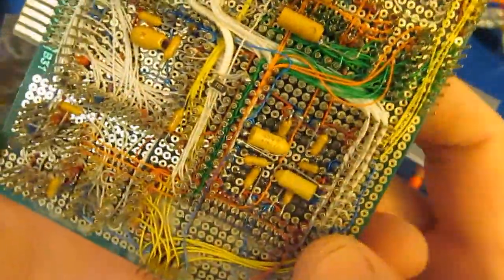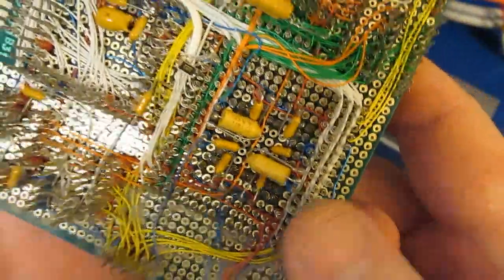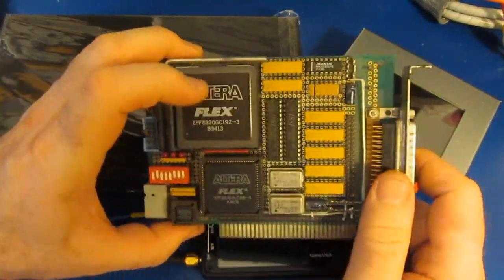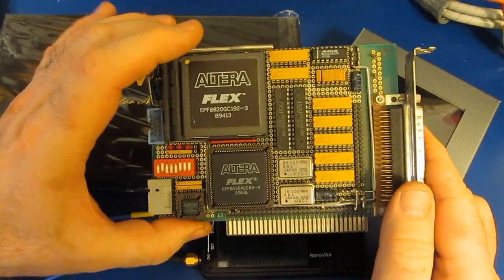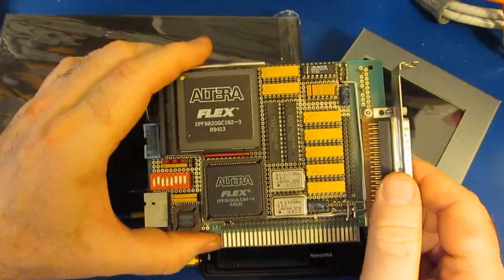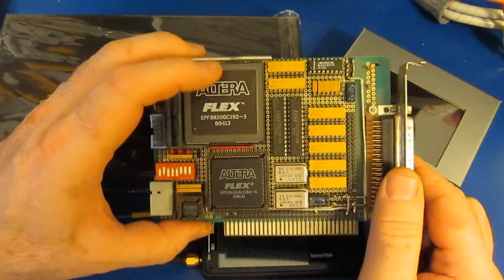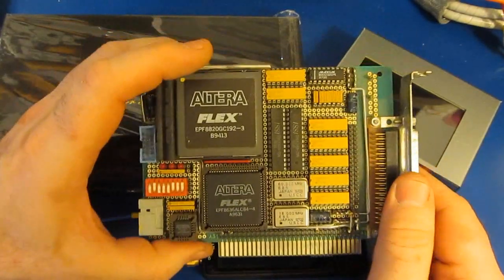So if we look at the larger FPGA, you can see there's different values being used. The FPGA and memory devices used on this particular board are all 5-volt logic. On modern FPGAs, the core voltages are much lower. So today, to properly design a PDN, it requires a little bit more thought.